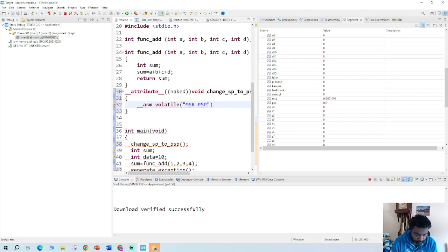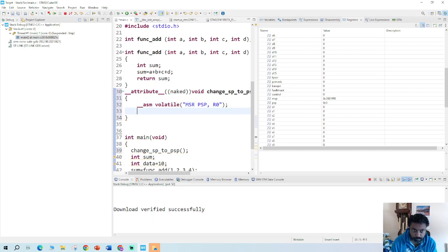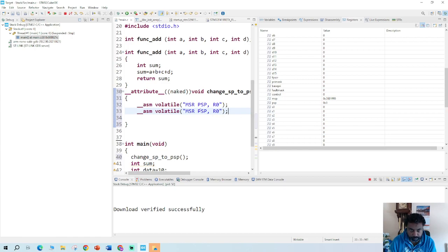and you're going to give the first argument value, the process stack pointer value. So this is where you let the processor know that you're going to use the stack memory. I'll simply copy this, and then now you have to set the SP select bit to say you're going to use PSP. So MSP will be changed to move R0 to a control location.